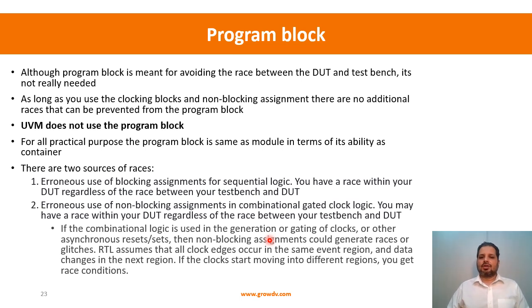So in those scenarios, there are certain guidelines. I am not going to go deep into how exactly those guidelines need to be followed when you do the gated clock, but if you do not follow them, then your clock itself is acting as logic, and it's participating in that whole process of evaluation, rather than happening once and letting the other logic execute. And that can again lead to race conditions.